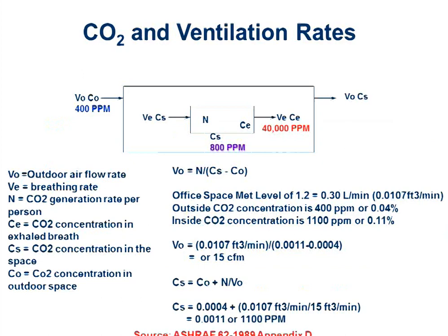So let's take a little bit to explain why CO2 is in the codes and which codes it's in and that kind of thing. So I'm not going to bore you guys with all the math because I don't think most people on this call are mathematicians. But this is the math that is straight out of the ASHRAE 62. It's been in ASHRAE 62.1 Appendix D for 20-some years. And in reality, the CO2 exhaling rate of human beings, it is what is used to set up the tables for the ventilation rates that are required by the VRP procedure.